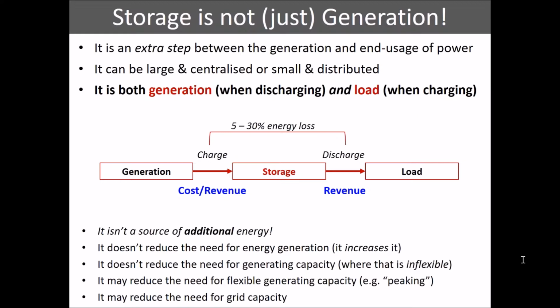We've already mentioned it can be large or it can be small. You can have huge-scale pumped hydro systems down to very small-scale battery systems. But the key thing for storage is that as well as being generation, so when you're discharging a battery or letting water out of your pumped hydro system, it's generating power, equally, storage can act as a source of demand. To put energy into storage, you've got to charge your battery or pump water up a hill. So it's unique in that sense that it's both a source of generation but also a source of load. So storage can play not just into management of supply, so variability of supply, controllable supply, it can also play into markets which value changes in demand.